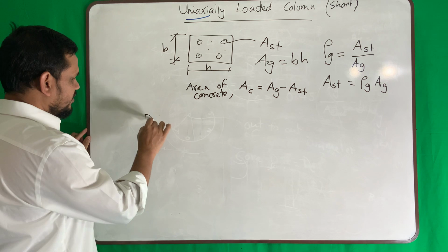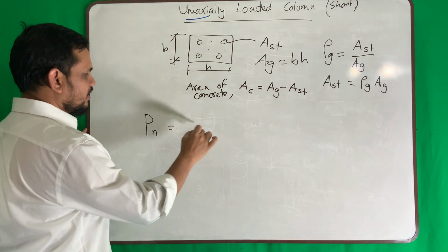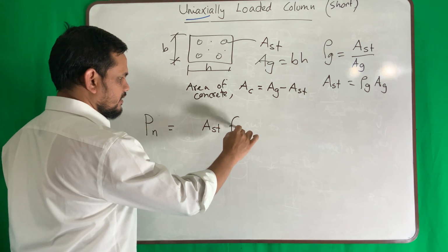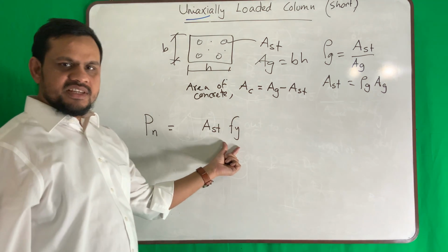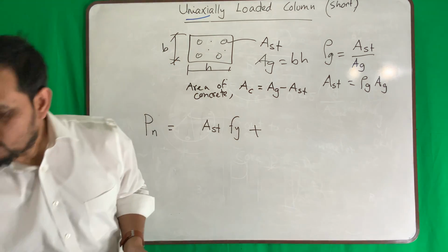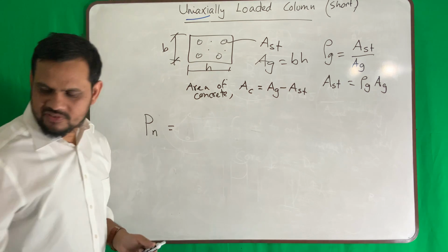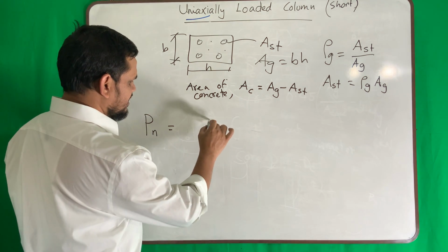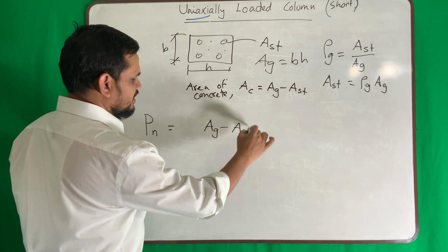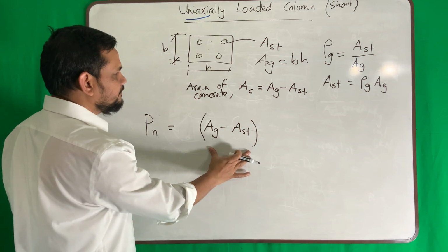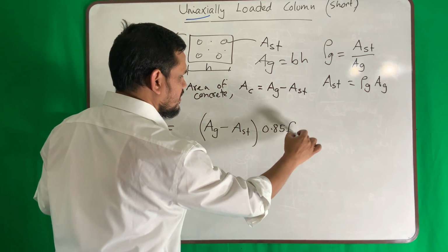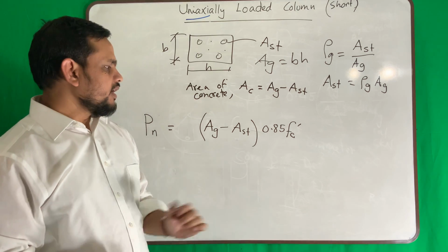So whatever load I apply, say it's Pn, then my steel will take load, area times stress is load, and then my concrete, or write concrete first. Why concrete first? There is no reason. I'm just writing, or it's mostly concrete. Okay, so concrete area times the concrete stress.